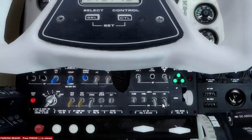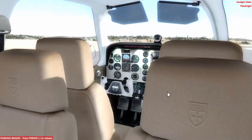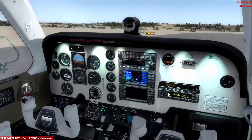I will activate the panel lights because I want to have a better light conditions inside the aircraft, and we will go little by little configuring the lights to take off. I will activate also the strobe lights, and I gave you before the charts indicating you how to use the lights properly. And very soon we will be departing.